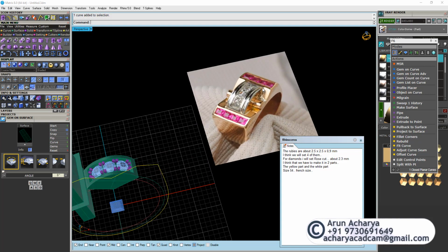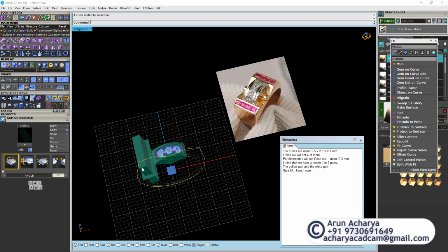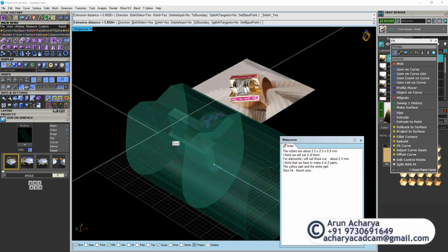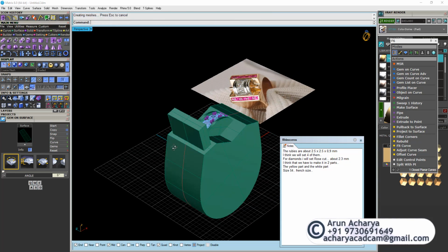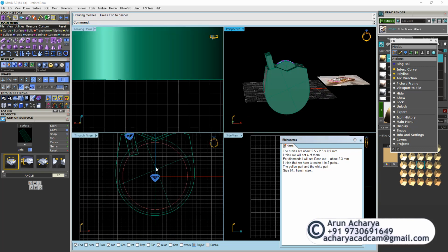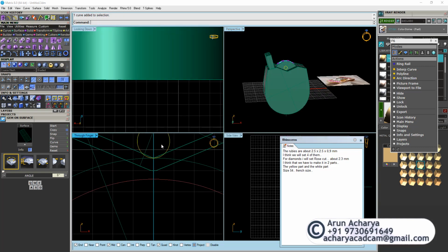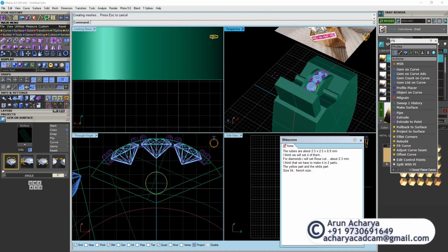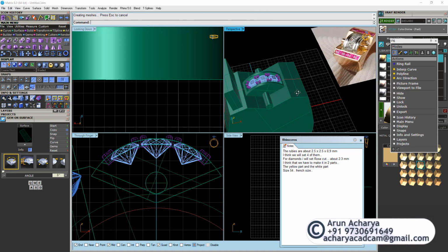We just need to extrude this shank, and later on we're gonna see how we can taper this from the side view. So extrude. We'll also extrude this pipe the same amount.